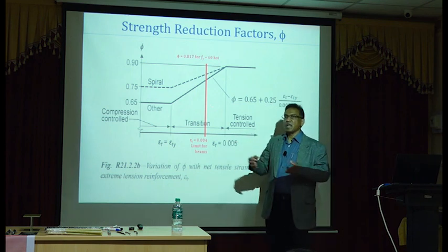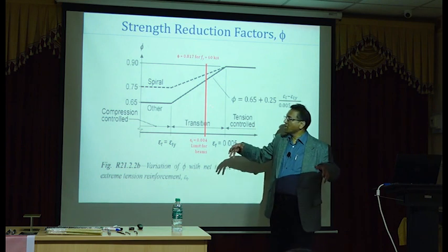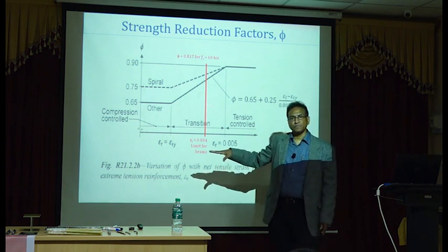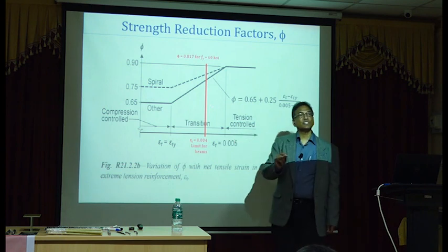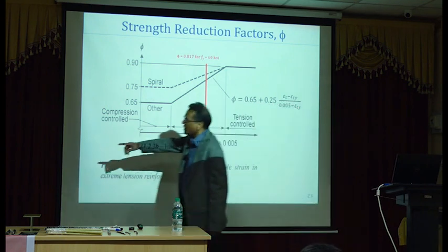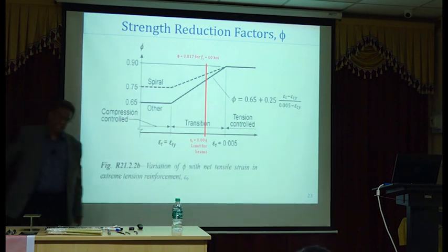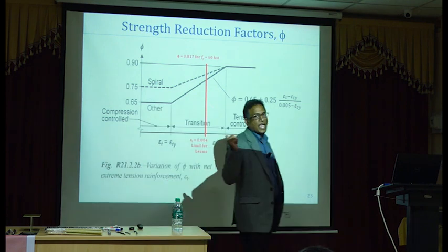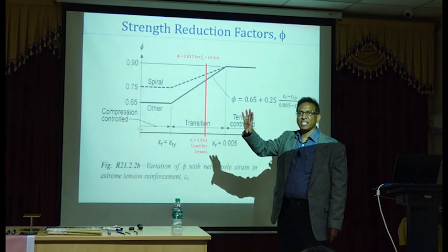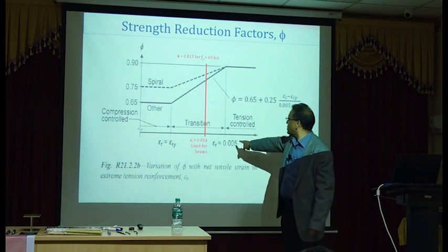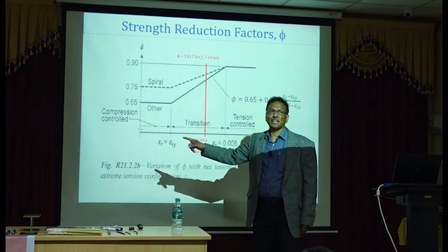If my beam is lightly reinforced, we can get very large strains at the bottommost layer of steel. And that large strain is defined as 0.005. I think we had 0.0038 here for IS 456. I think there is a reason why they have that smaller value. Because your depth to neutral axis is larger, therefore, if you want to satisfy this 0.005, you'll be struggling with it. Does it make any sense?